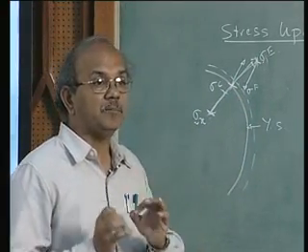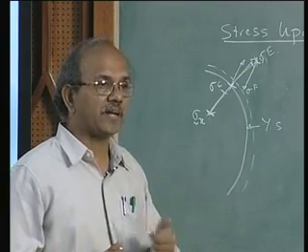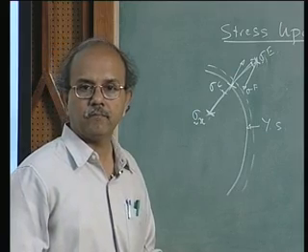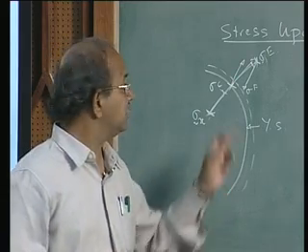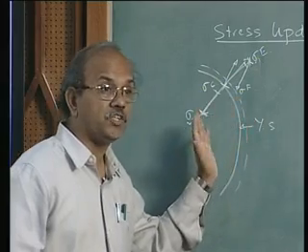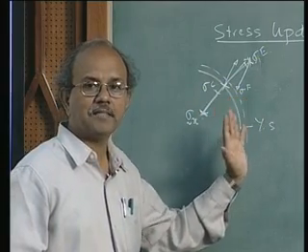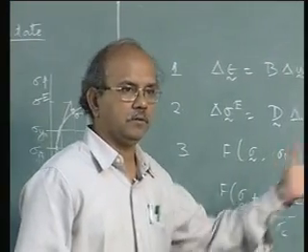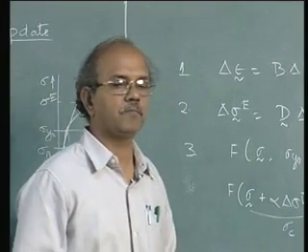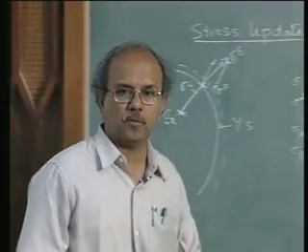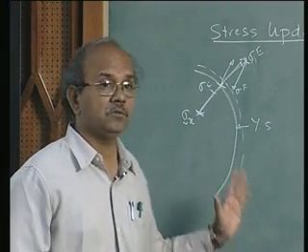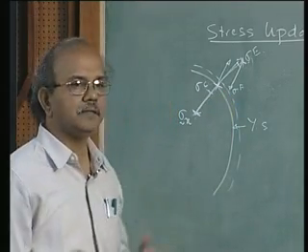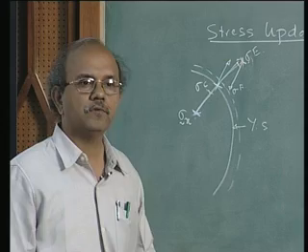Now there can be a confusion at this point. How am I right in taking the normal at the contact point? Because the yield surface is also going to progressively change or expand as I now calculate the stresses using the elastoplastic conditions. In other words, I will calculate the elastoplastic strains, and this will help me to expand the yield surface. So how am I correct to take that as the point where I calculate the normal?